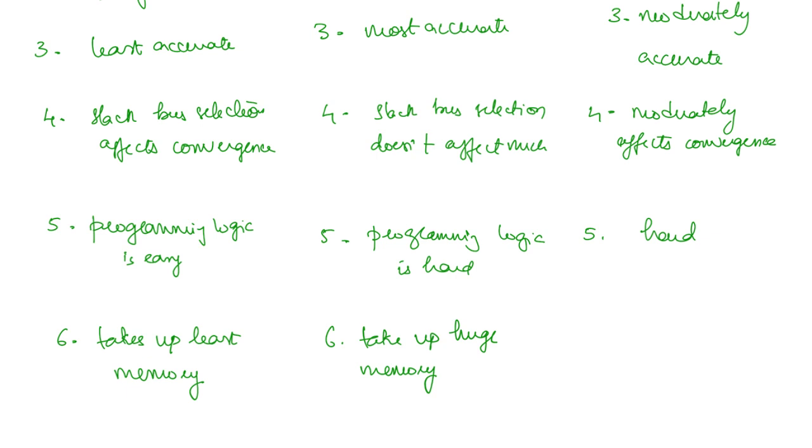Okay, what happens in fast decoupled? This is the major advantage of the fast decoupled when compared to the Newton-Raphson method. It is going to take much less memory compared to Newton-Raphson method. Why? Because two of the sub-Jacobian matrices we have equated to 0. Okay. So that is how the memory that is required for fast decoupled flow is going to be less than the Newton-Raphson method.